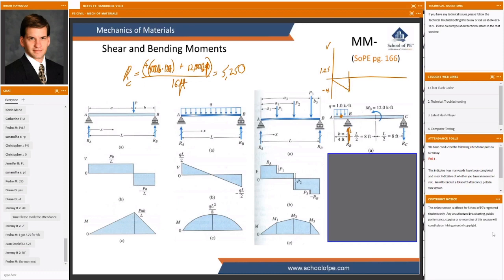And then we'll carry right on across. What do you suppose reaction force C is? Well, if this is 4,000 pounds and this is 5,250, then reaction force C must be a downward 1,250. So reaction force C brings us back down to 0 as predicted, 1.25 thousand pounds. So there's our shear diagram.